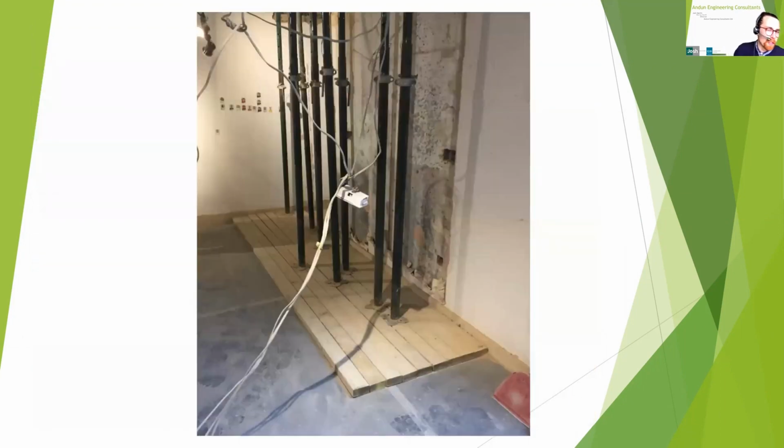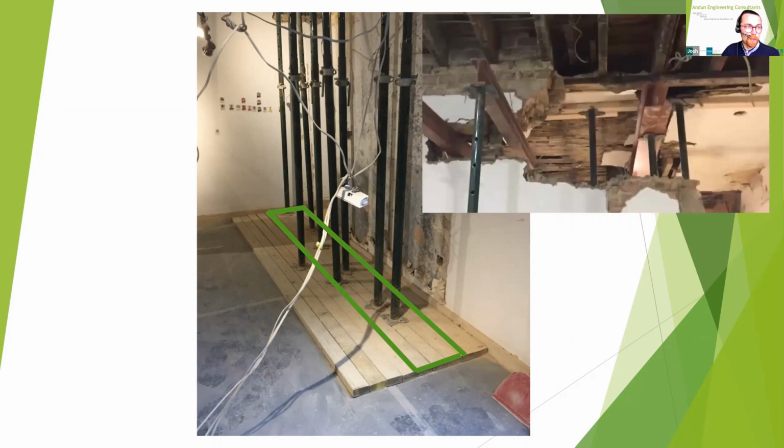Also, the foundation of this propping was on a raised floor, and so they clearly thought, well, we might need to put some timbers down to strengthen it, but this certainly is not good practice. The timber should be concentrated in the zone where the props are loading, which is shown there. And if there's enough timber to double stack, that would go a long way to provide additional load spread across the floor. But after looking at this, it's questionable if some of these props are loaded at all. But that's some bad practice and things certainly to be avoided.